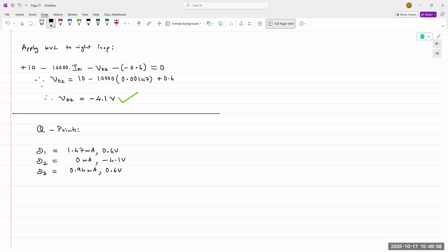So if you write the same equations, the same procedure, everything, except instead of 0.6, it would just be 0. So one less term to calculate. But ideal diodes are great if I just want to analyze a circuit and see what is exactly going on. So I just put on, off, on, off, on, off. It makes it easier to analyze, which is a technique I use to explain rectifier circuits.